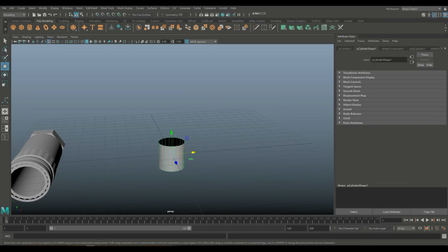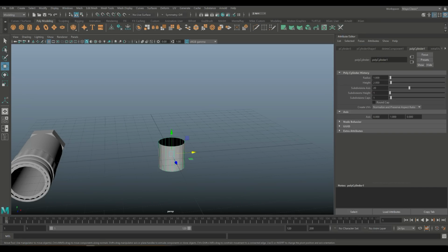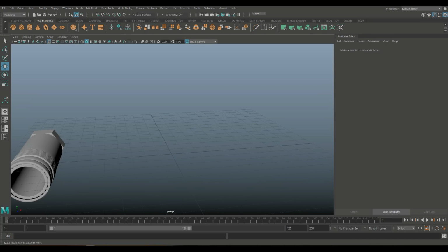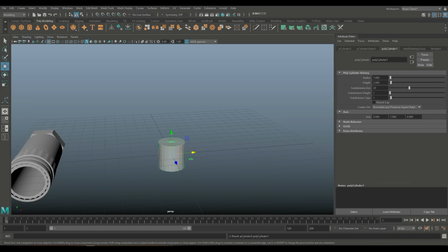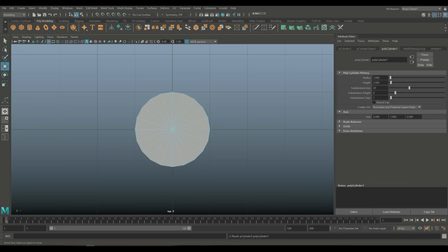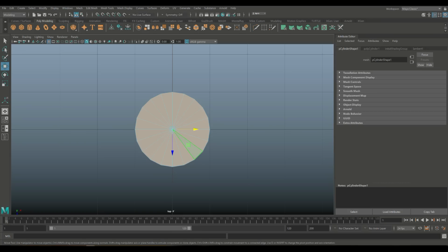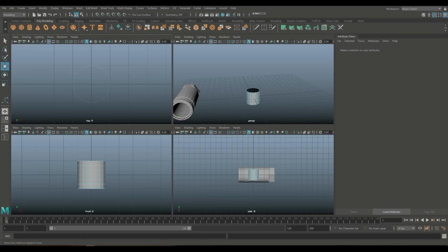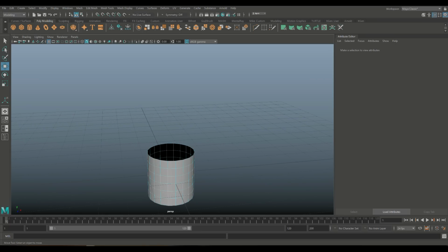And let's see, we're going to go in here and let's set height subdivision to, let me try that again, guys. Sorry, here we go. Let's set height subdivision to, let's do 6 for now, right? Okay, then we're going to go to the top, we're going to right click at a face, drag select, delete. So that's what we have.